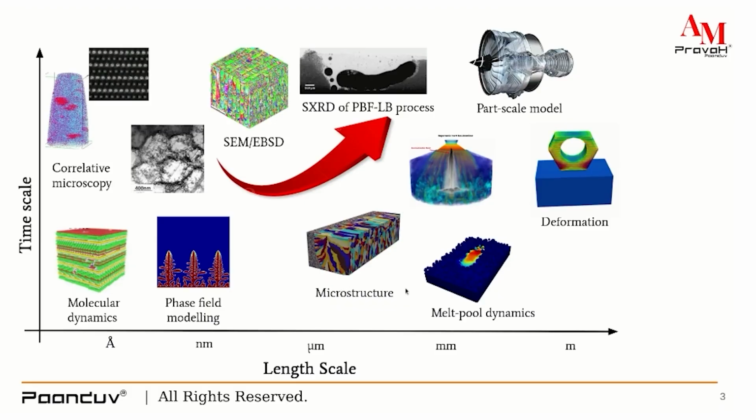We do microstructure analysis by using Monte Carlo algorithm, and this microstructure evolution will give you a 3D grain evolution analysis and deeper information about how and why these grains are evolving in such a manner, and you can get all the temporal as well as the spatial information about these evolution methods. At part scale, which is a very important scale, again, you can get information about deformations, the stresses generated in the entire part, and the problematic areas.